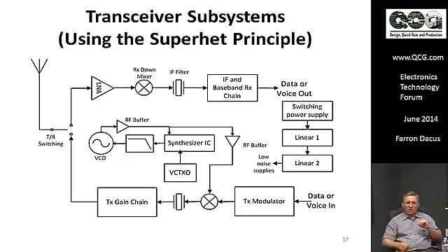And that phase noise, I'll show a graph of it later, is coming up as frequency comes down. And so you reach a point where you become phase noise limited in sensitivity. Jitter on your oscillator. Right, and that sets a lower limit on how low you can take the data rate or the bandwidth. So it looks great on the data sheet, but maybe doesn't get you the link budget you think you're getting. Well, they may be telling the truth because there's a way out of this trap.